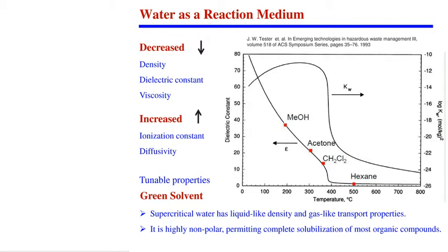The question comes to energy balance. Immediately when we talk about high temperature, we think it's an energy intensive process. But it's not like steam based processes. I'll try to explain. Most biomass contains water. If you want to compare a steam-based process versus a subcritical water-based process, a steam-based process means you have a vapor phase. That means a phase change is required when you make steam, and the latent heat of vaporization is 2.26 megajoule per kg.